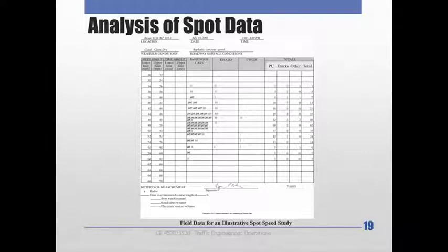You're undercover cop. So anyways, what we're going to do, we're going to set our speed depending on the speed limit. So we can say, for example, I'm going to have different speed groups. Here we're looking into 30 to 32, 32 to 34 in 2 miles per hour intervals. And then I'm going to count how many vehicles are actually at that specific speed group.